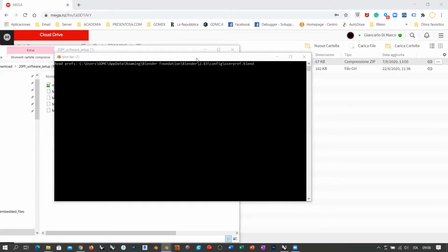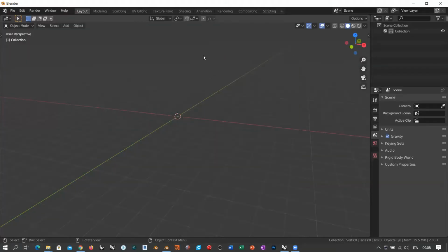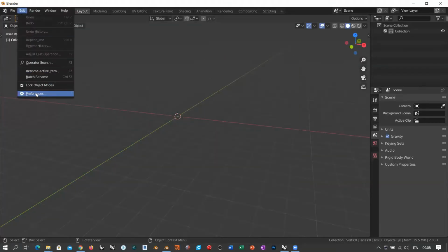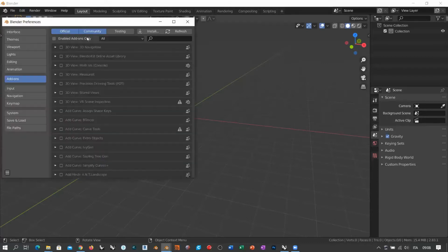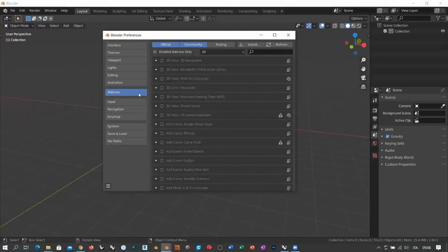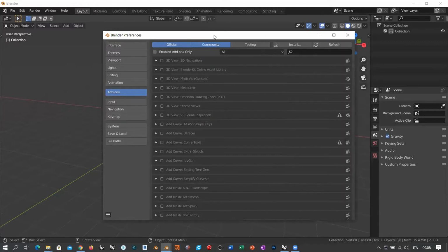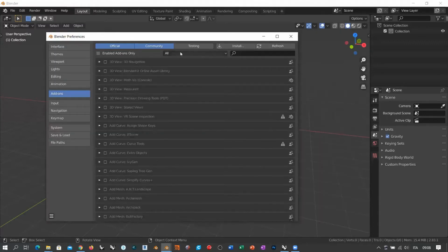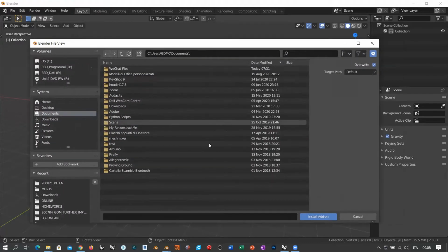It's very simple, actually. When you open Blender, you already know that there is this edit preferences where you have these add-ons interface with all the list of the available add-ons. And you can install new add-ons by simply loading the Python script. So in this case, you just press this button and go searching for the py file.